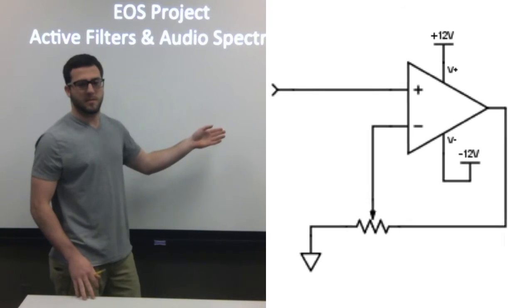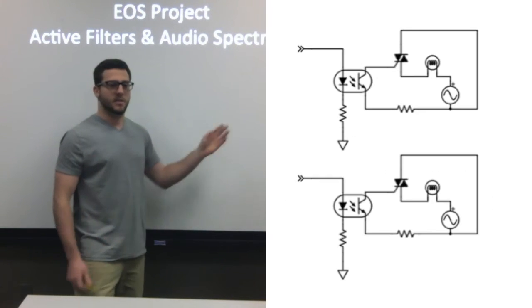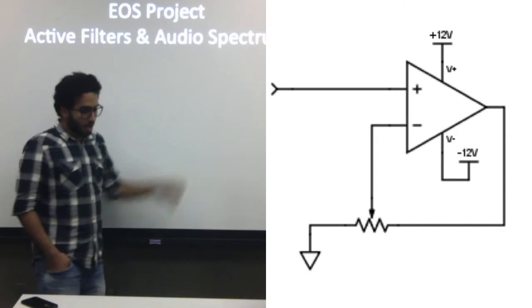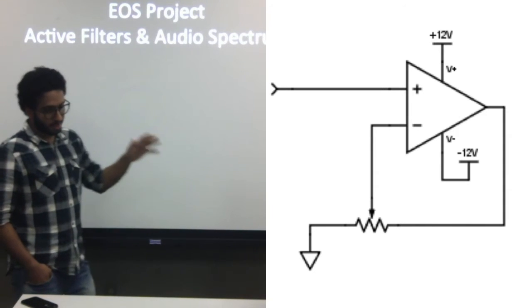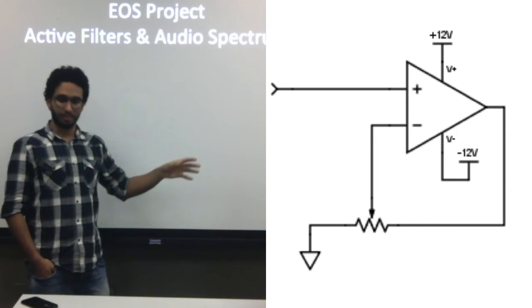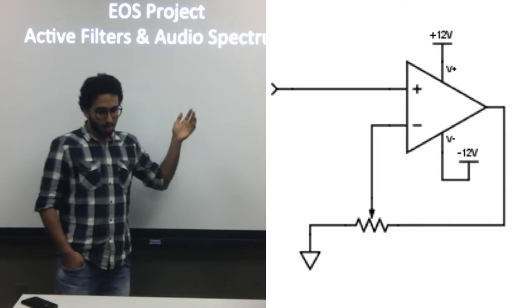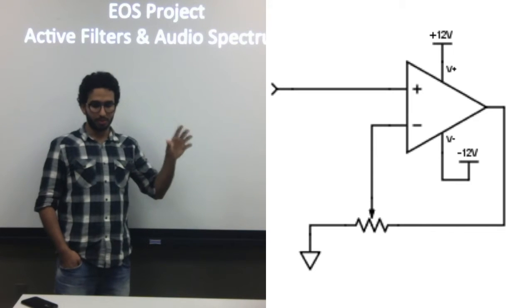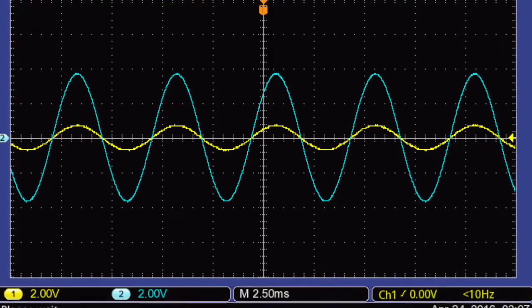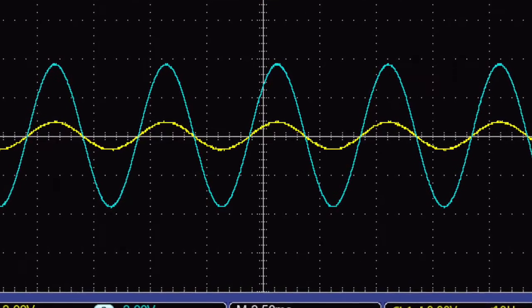The amplifier subsystem, the high and low pass filters, and then the triac subsystems. The first subsystem is the amplifier. This takes in the audio input and amplifies that signal 4 times and sends that signal to both of the filters. The amplified signal is needed because the input amplitude is too small. Here this waveform shows channel 1 across the input to the amplifier and channel 2 across the output.